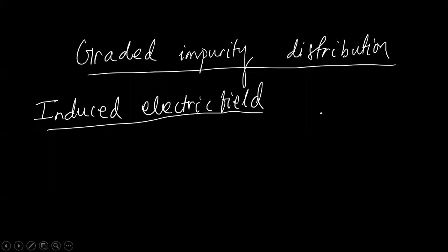Hello guys, today in this video we are discussing graded impurity distribution, and because of this graded impurity distribution, what will be the induced electric field? Okay, so now let us first try to understand what is graded impurity distribution or non-uniform doping, all right?